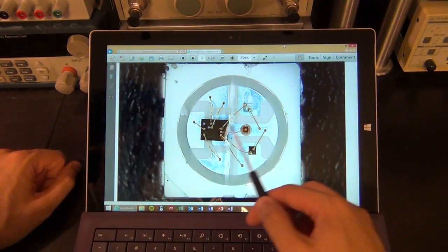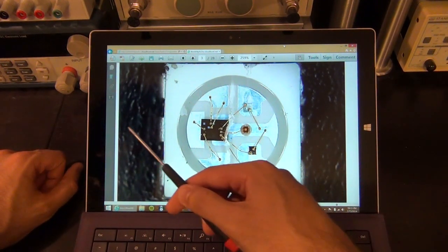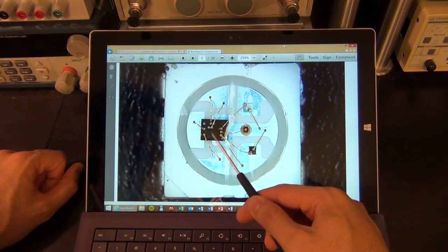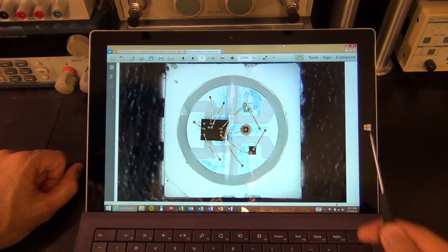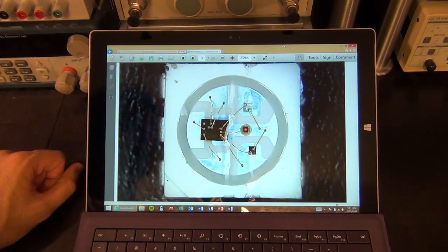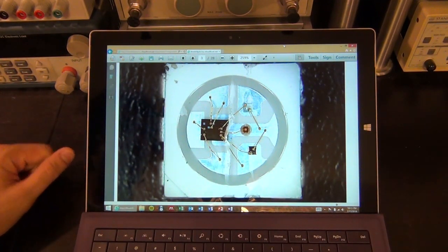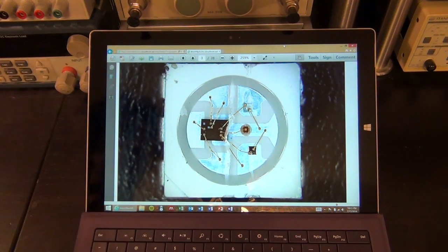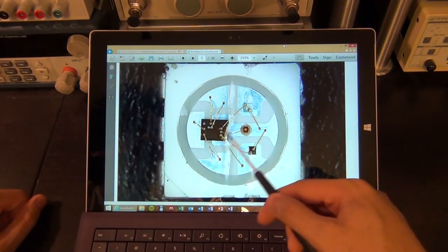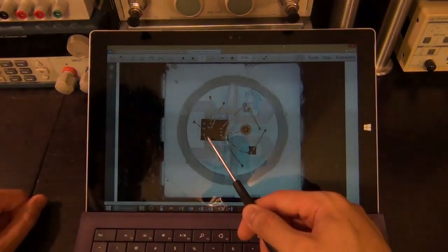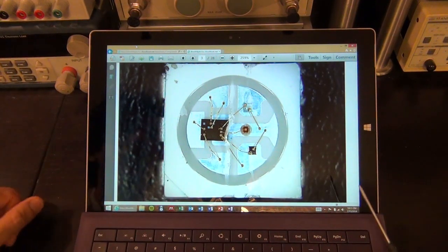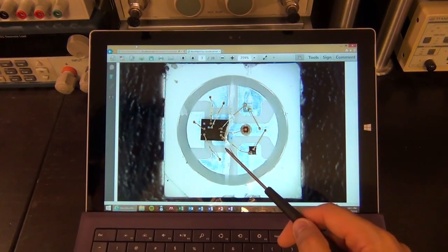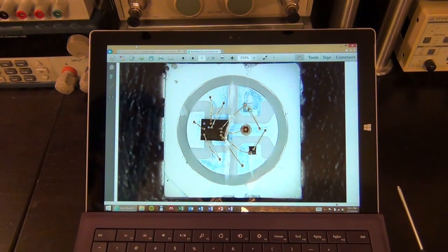For example, let's say there are only 2 LEDs in a row. You put in the first 24 bits, it gets stored in this one, and then once you push in the next 24 bits, the first 24 bits are pushed to the next LED. So it's essentially like a very long shift register that you're dealing with, except that there is no clock. It's an asynchronous shift register. So you push 24 bits, it gets stored in the first LED, you push in a second 24 bits, then the first 24 bits get pushed to the second LED, and the last 24 bits remain in this one. And then you hold the data line low for long enough, and voila, both of the LEDs light up with the 24-bit data that's been stored in them.